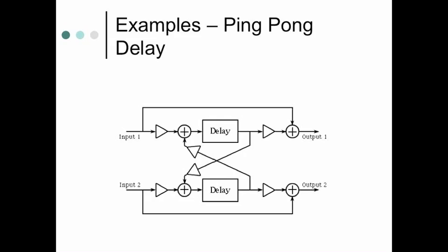But let's say you put in a signal that looks like this, so there's charge, and then no charge, and more charge, and no charge on this plate, and induced charge comes and goes on this plate. So in a sense, it jumps the gap from one plate to the next. When you get to a high enough frequency, it starts looking like a complete straight wire where electrons can move through. So that's how this becomes a frequency-dependent device. You combine that with a resistor, which is not frequency dependent, and you can make filters and EQs and all sorts of manipulation of spectrums.